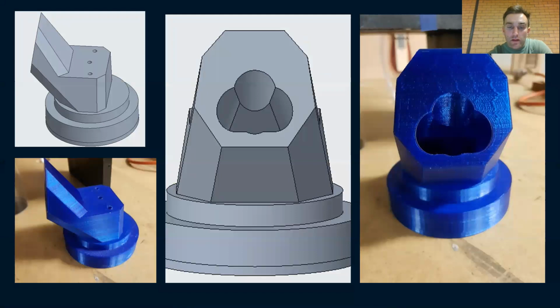In order to try and validate this method, I'll compare the mass flow rate results that are computed in the port flow simulations alongside flow bench results from the standard port mass flow rates of the 4AGE head. I also 3D printed a test piece of my inlet port to flow test as a second check, which is the blue model seen here.